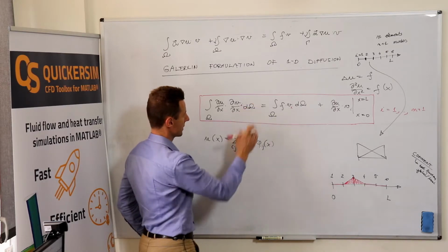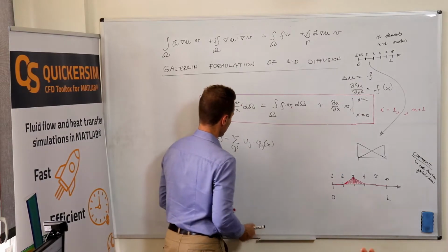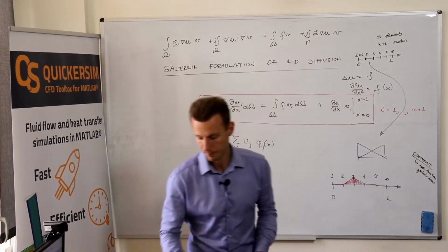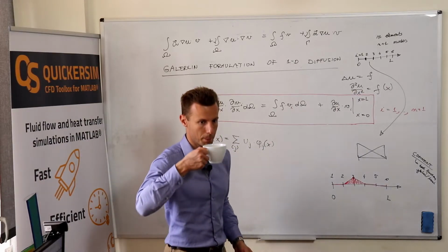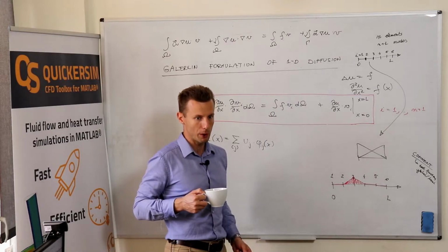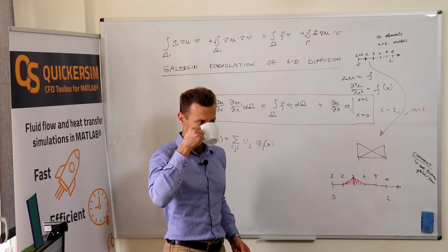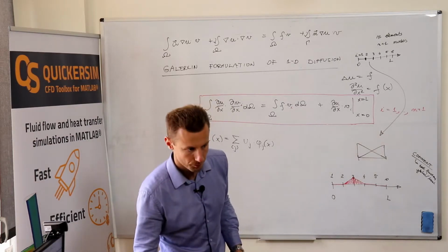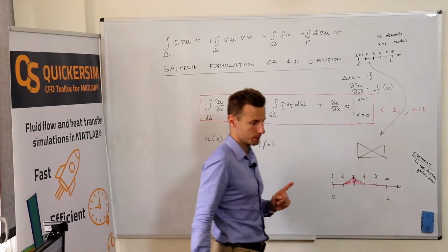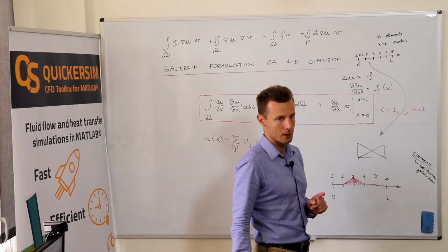So let's do the discretization. And there's not much to be done. Why don't we use some non-linear function? For example, like that. If you define that a single line element has only 2 points, then you can use only linear functions because you can only span linear functions on 2 points. But if you have 3 points, you can have parabolas.